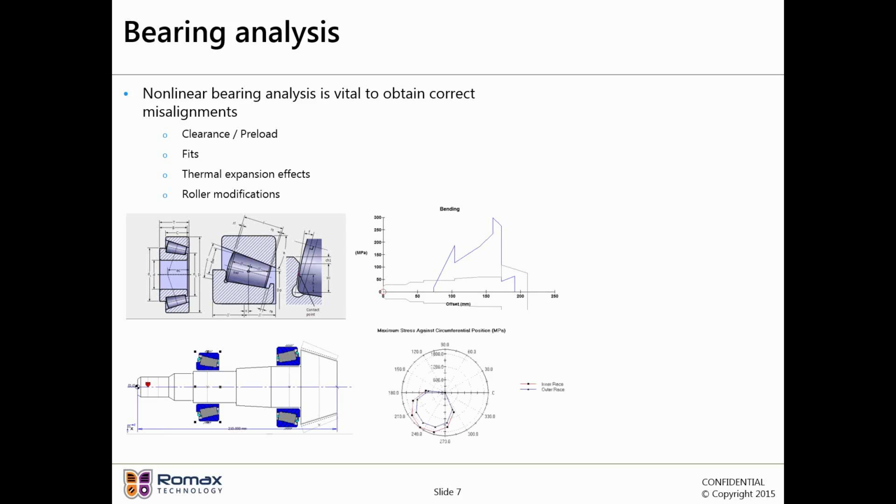And it calculates the bearing load distribution. That shows the stress on the rollers. You see the load has been pushed towards the bottom left in that picture, and the rollers in the bottom left quadrant are all loaded. That graph shows the peak stress. This graph shows the stress distribution along the length of the rollers. So here you can see there's a slight misalignment because the load is pushed more to the right of the image.